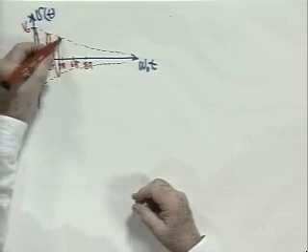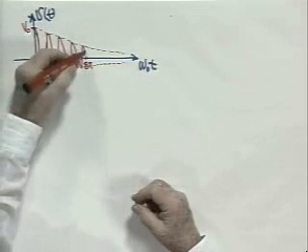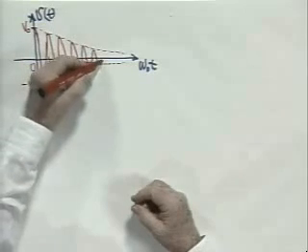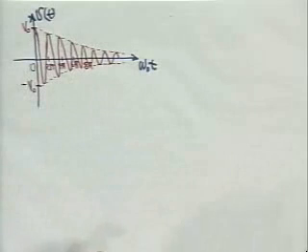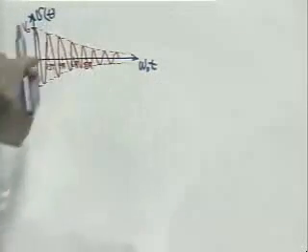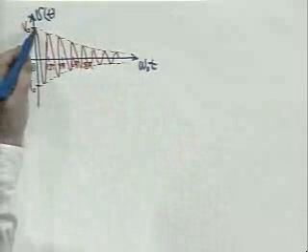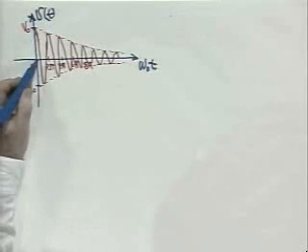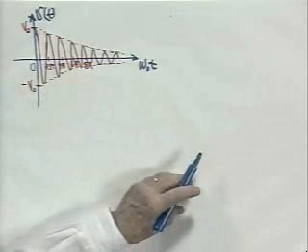Comes back to a smaller value. Likewise in the third period, and so on down. So the response is a cosine attenuated by this function e to the minus alpha t. And the current, were I to draw it, would have exactly the same form, only it would start out not at a finite value, but at 0, and be 90 degrees out of phase with this cosine function.